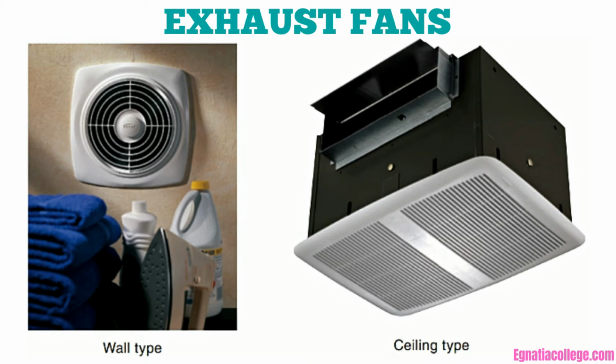The fan unit terminates in a metal hood or grill on the exterior of the house. The fan has a shutter that opens as the fan starts up and closes as the fan stops. The fan may have an integral pull chain switch for starting and stopping, or it may be used with a separate wall switch. In either case, single-speed or multi-speed control is available. The fan in use has a very small power demand, 90 volt amperes.